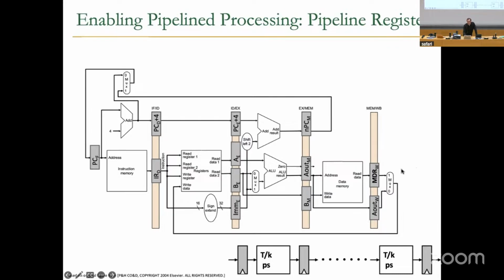So once an instruction reaches the write back stage, if it's writing to the register file, it writes the data. If it's a load, you write the data that was latched in the previous cycle while the load was in the previous stage from memory. If it's an ALU operation, then you write the data that is the result of the ALU, right? As we have seen in the single cycle data path, actually. So basically, you should be writing the data, no question about that.